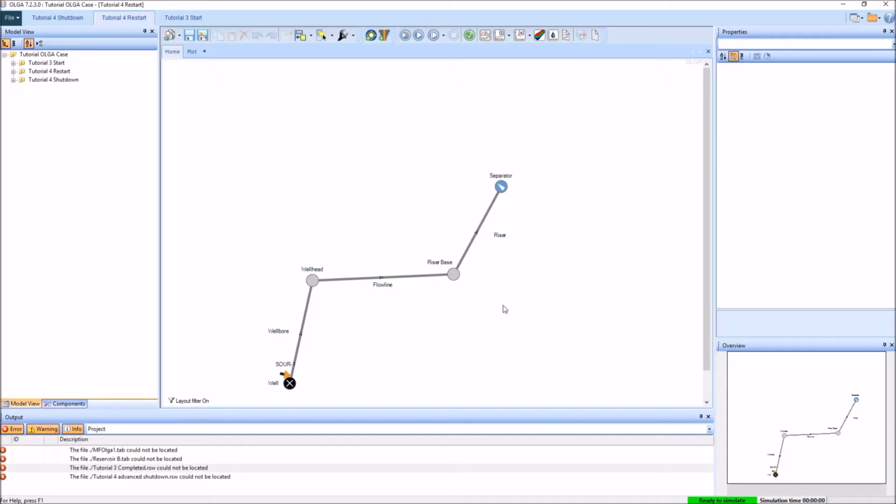Now, first things first, what are hydrates? Well, basically, you can think of them as ice that forms at high temperatures. So you might get hydrates forming up to 20 degrees C in your pipeline if the pressure is high enough. And you can imagine that if you have these solid ice-like particles forming within your pipeline, this can cause some serious problems for you. So when we're simulating hydrates in OLGA, we again have to make use of both Multiflash